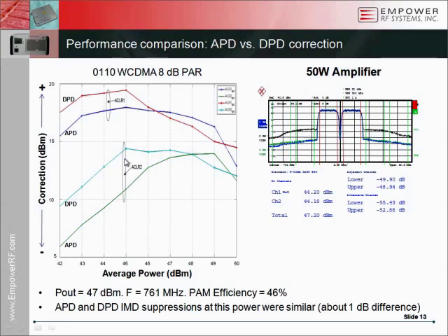Yeah, I mean, in a typical radio head, I wouldn't say that the transistors are the worst culprit as far as junction temperatures. I think most transistors are designed effectively to be under 150 degrees, and you can even operate much higher than that, in my opinion, with reliability. We've done studies that you can operate at 175, but we don't. No, not many people do. There are other things like the DSP, the FPGAs, other things that are hot that contribute to the overall reliability number. So. Right, and then